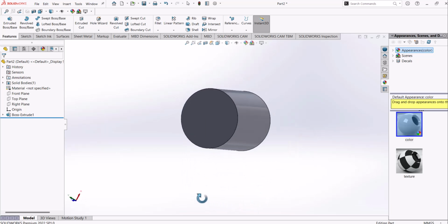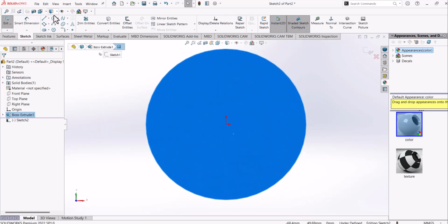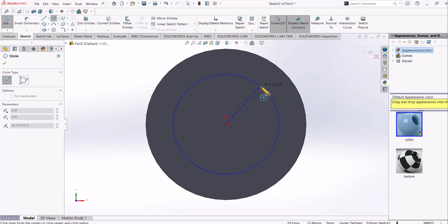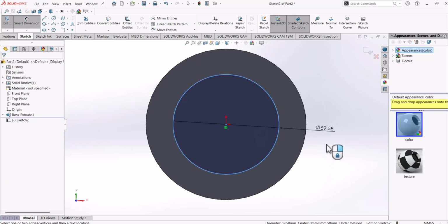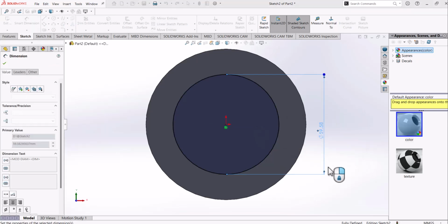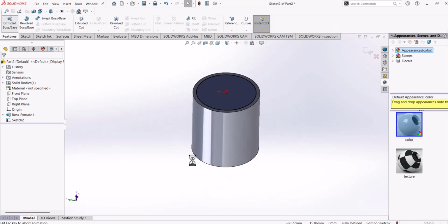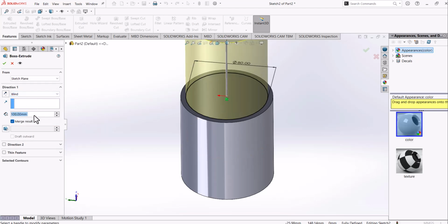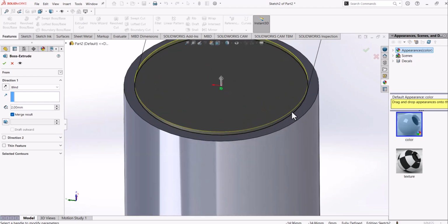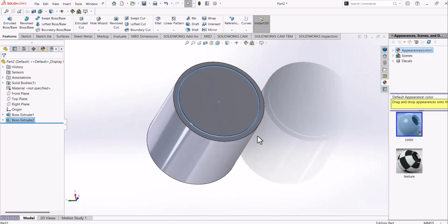the surface, now select here, sketch. And that happens to be 80 millimeters. So 80. Select the surface, let's make it 80, set, and go to extrude. We'll extrude this time around, we'll make it 2. Upon doing this, you get this small extrusion. We accept. So good, this is what we get.